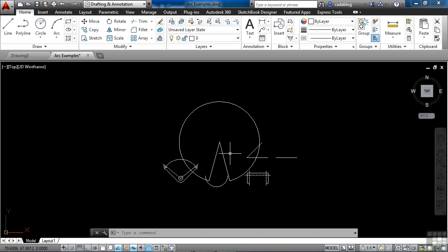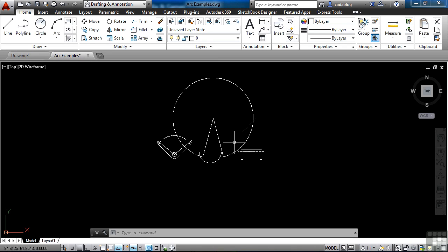This will make your first point the center point of the arc, and it will make you draw all sorts of arcs. So now you have 2 ways to draw an arc, from a start point to a point in between and then to an end point. Or now you can start at the center and get your start and finish points and at that defined radius. Now, you don't always know these points. That's what's great about the arc command. The majority of what you're going to need for your arc command are the 2 that I just showed you.